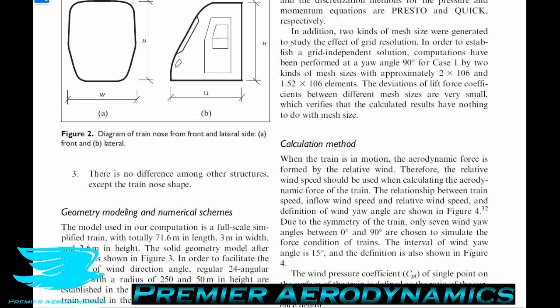The reason why this is important is because the density of air always changes. For example, if you come into your wind tunnel in the morning, then come back after lunch, the density of air has changed by a few percent in just a few hours. It's amazing. That's because the density of air is affected by the temperature, barometric pressure, and humidity. And all these things do change all the time. So, we know when we wake up, it's colder. At midday it's warmer, and the barometric pressure fluctuates as well, as does the humidity.